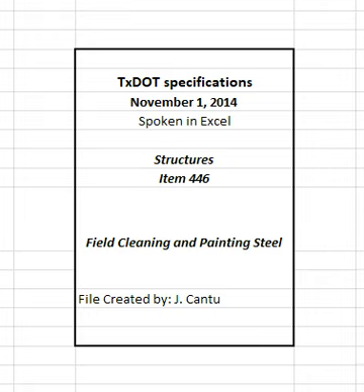4.7.3.2.1 Abrasive blast cleaning. Meet the surface preparation requirements of SSPC SP10 unless otherwise shown on the plans. Ensure a minimum profile of 1.5 mils. Do not add depth to existing profile when the surface profile exceeds 4.0 mils. Measure surface profile in accordance with ASTM D4417, Method C, Standard Test Methods for Field Measurement of Surface Profile of Blast Clean Steel. Containment mounting points and other repair areas under 1 square feet may be tool cleaned to SSPC SP11 with at least a minimum 2 mil profile when approved by the engineer.